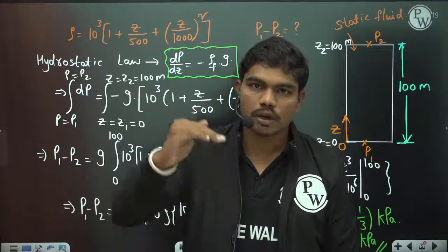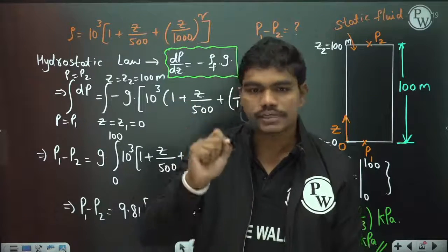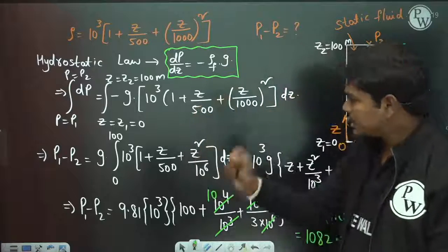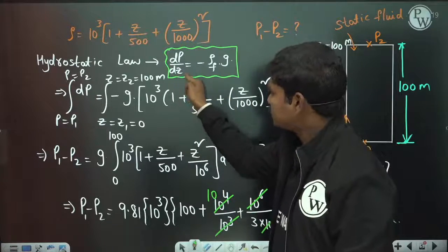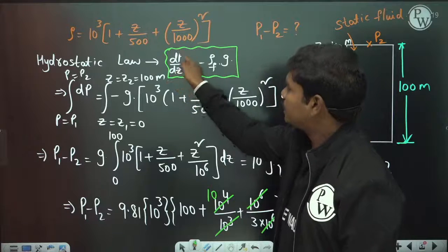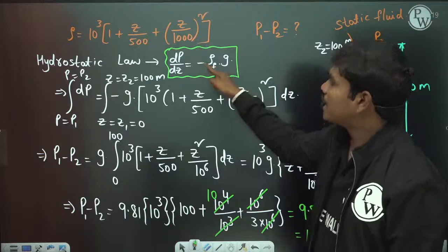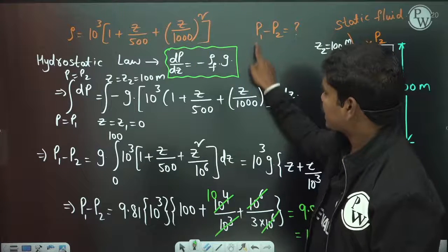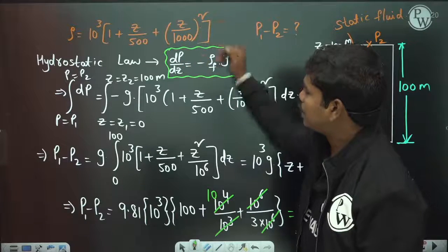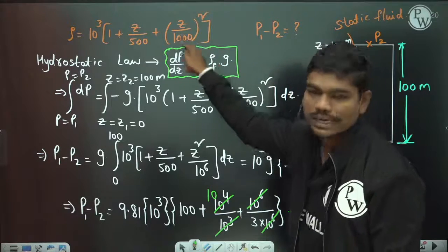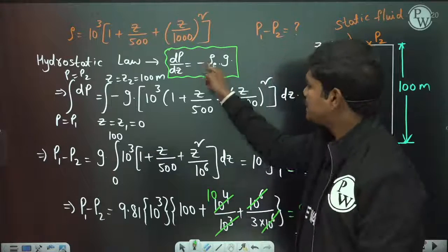Obviously, as you are moving up in the positive Z direction, the pressure on your hand will actually decrease, correct? So when the pressure is decreasing, a positive change in Z, meaning Z2 minus Z1 is positive, then dP, the value P2 minus P1, will be negative. That's why there is a minus sign here: if Z is taken in the positive direction and you increase the value of Z, the change in pressure is negative, the pressure actually drops. So that's why there is this minus sign.